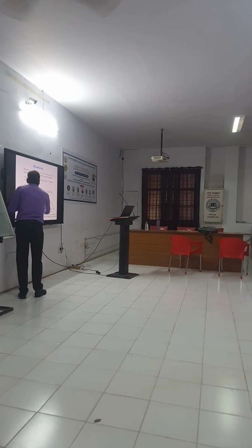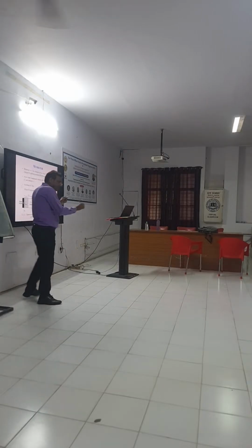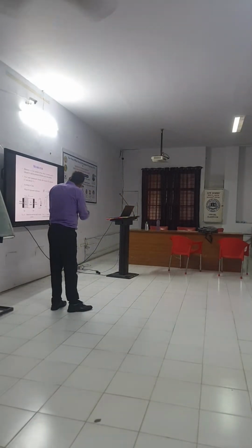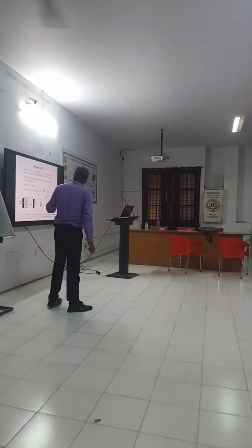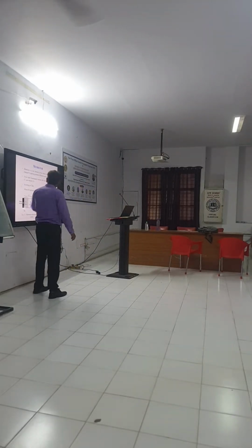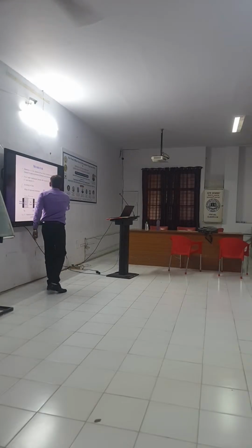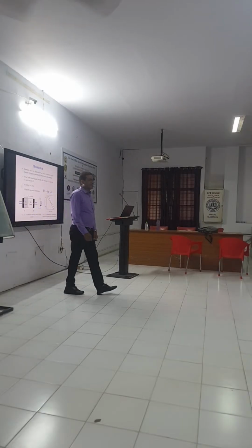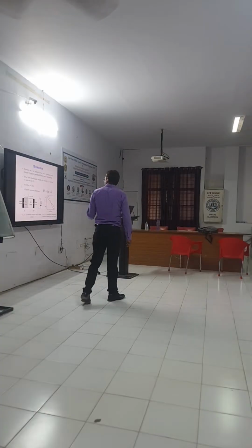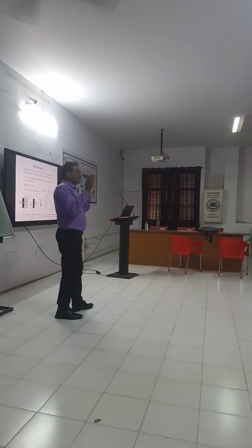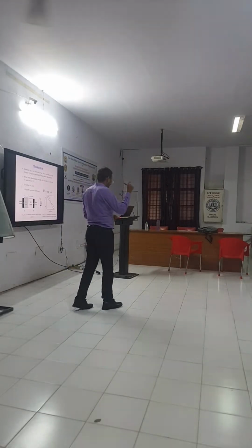When this W increases and becomes equal to D, the resistance will be very low. So it is more resistive or less resistive depending on the potential. Its symbol is like this. If you draw its voltage transfer characteristics, it looks like a hysteresis curve. Due to this, there is an inversion result. If you remove the power, it will still store the voltage across this device.